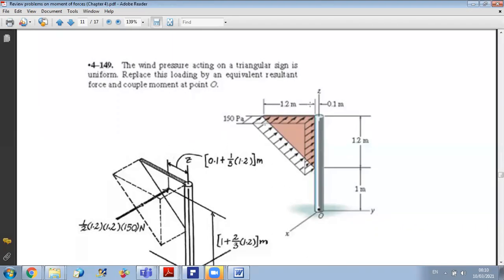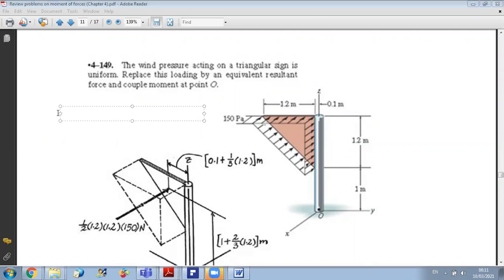So, by analogy between 2 dimensions and 3 dimensions, okay, we said that in a linear load, the resultant force is equal to the area under the curve. Okay, now in 3D, the only difference is that we have, instead of area, a volume. So we can say that in 3D, the resultant force Fr is equal to the volume under the distributed load.